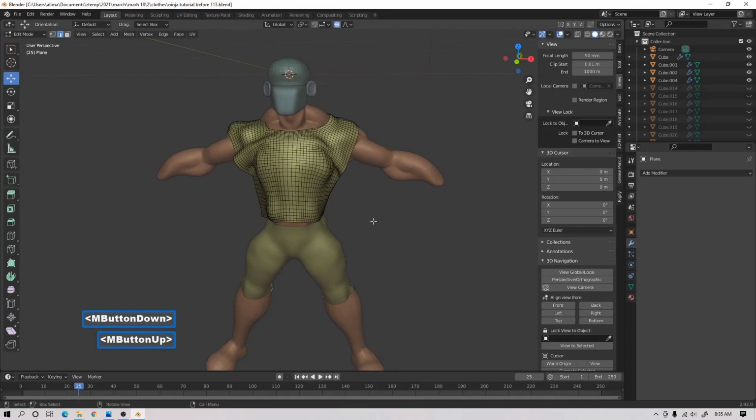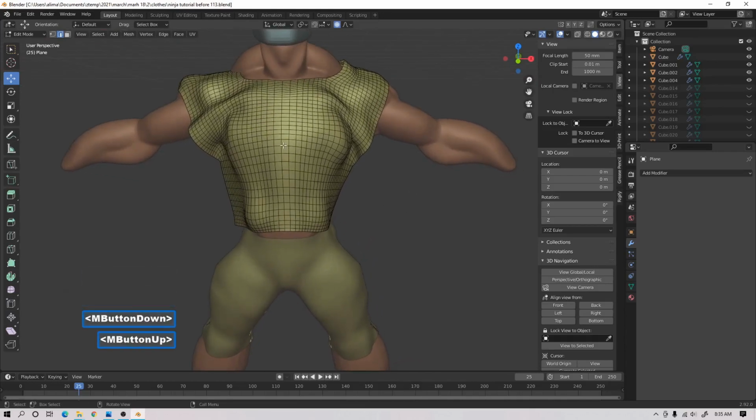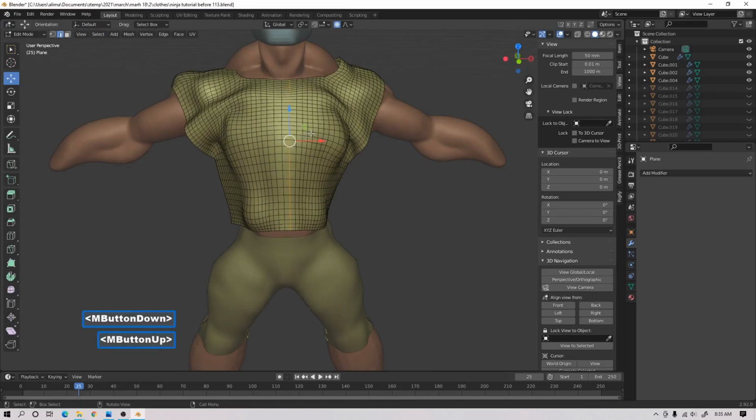Okay, we want to split this down the center. So what we're going to do is we're on edge select, which is good. We'll hold Alt, select this center, or close to the center anyway. I have my mouse to the right of this selected line. So now what I'm going to do is press V. See that? So I ripped this line, which in a way is separating this side from that side, all right?